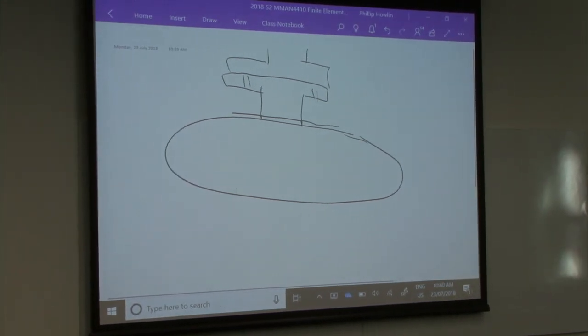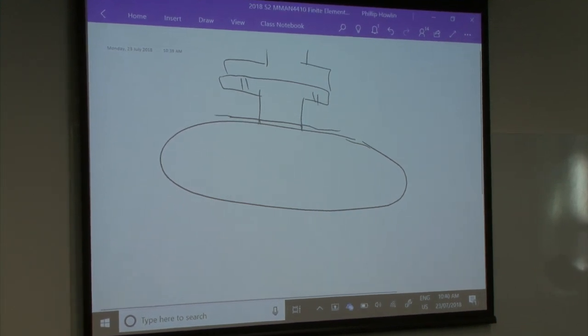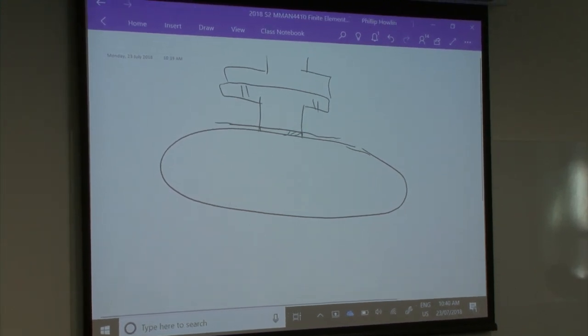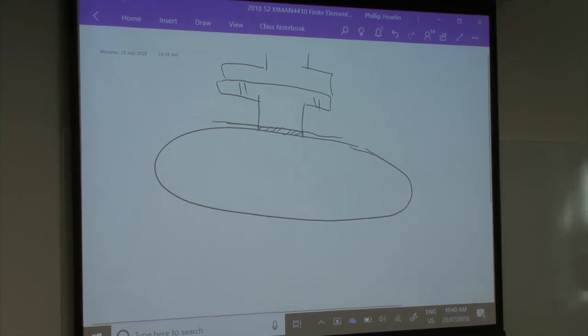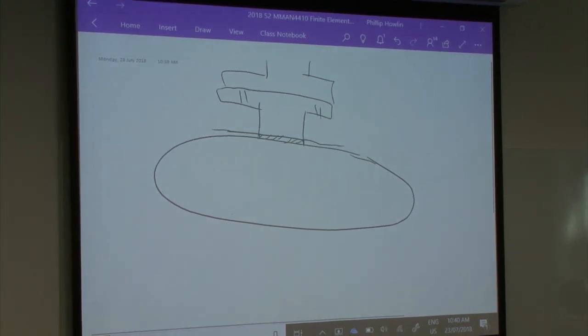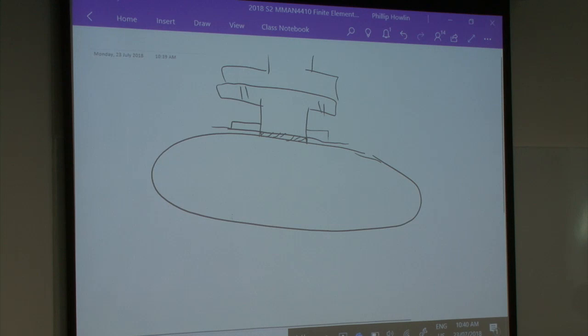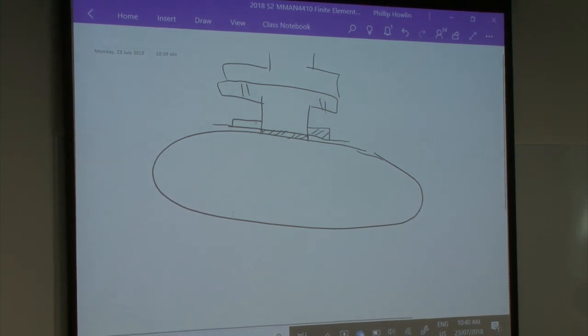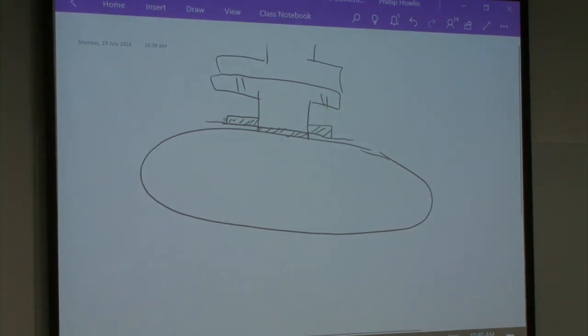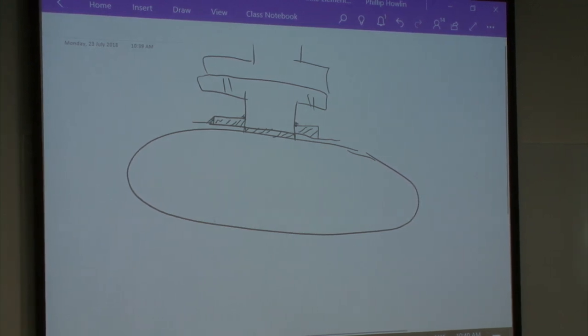Basically, what the Australian standard says is, you cut that much cross-sectional area out of it, so you have to add at least that much area there and there. So the area you remove must be the area that you put back in. And I'll put some welds there. That's called a compensation plate.